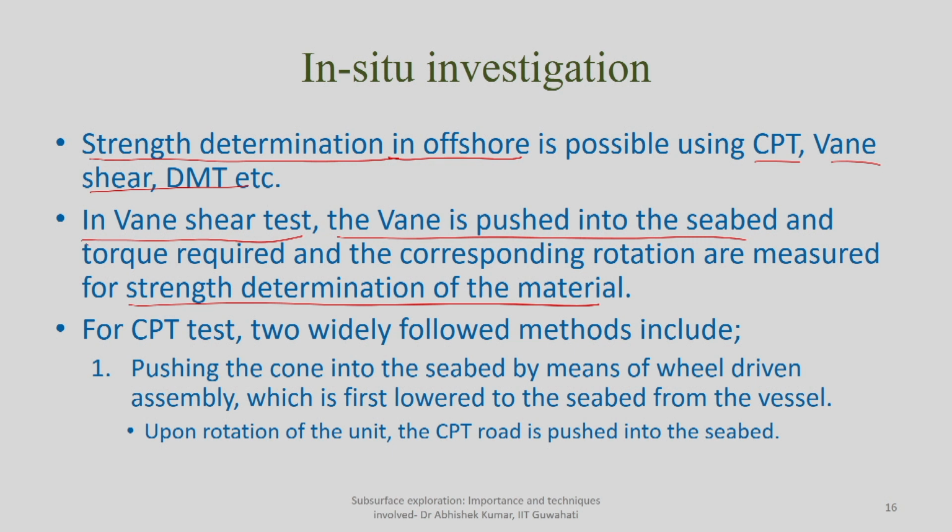environment. Now, when we go for CPT test, there are two widely used methods. Again, in CPT test, the more common practice is to do the test from the seabed itself. So, the entire assembly will be installed at the seabed, or will be there at the seabed, and from there onward you actually start pushing your rod. And if you recall, in case of cone penetration test, we precisely go for two measurements. One is the cone tip resistance, and the second one is your skin friction or sleeve friction.